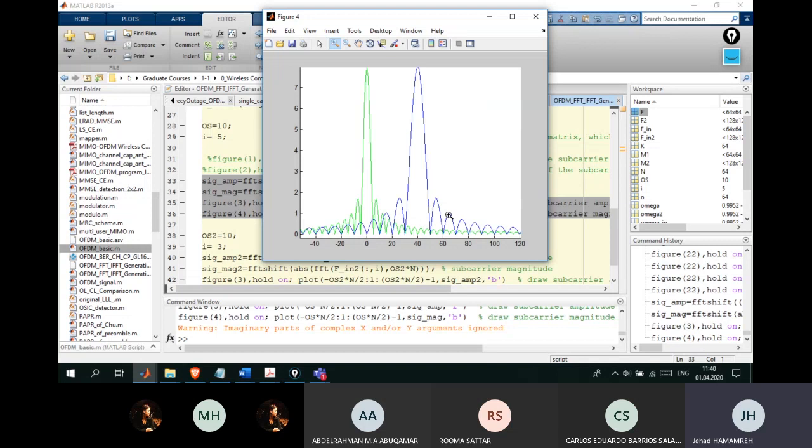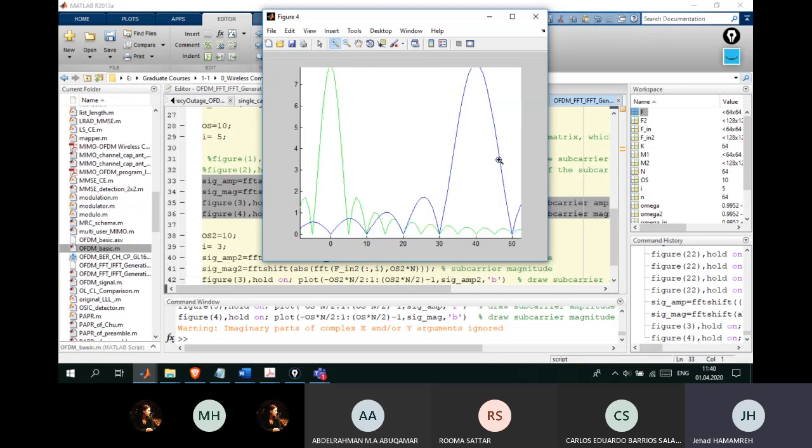You now draw, this shows you the drawing of two subcarriers, one blue and one green, and you are basically asking which one has larger subcarrier spacing? This one. So you can assume this is 30 kilohertz, and this is 15. When you put enough spacing between them, I was able to put them with no interference to each other if I place them at this distance. But this distance, I want to reduce it. I don't want this to happen, just because this is wastage.